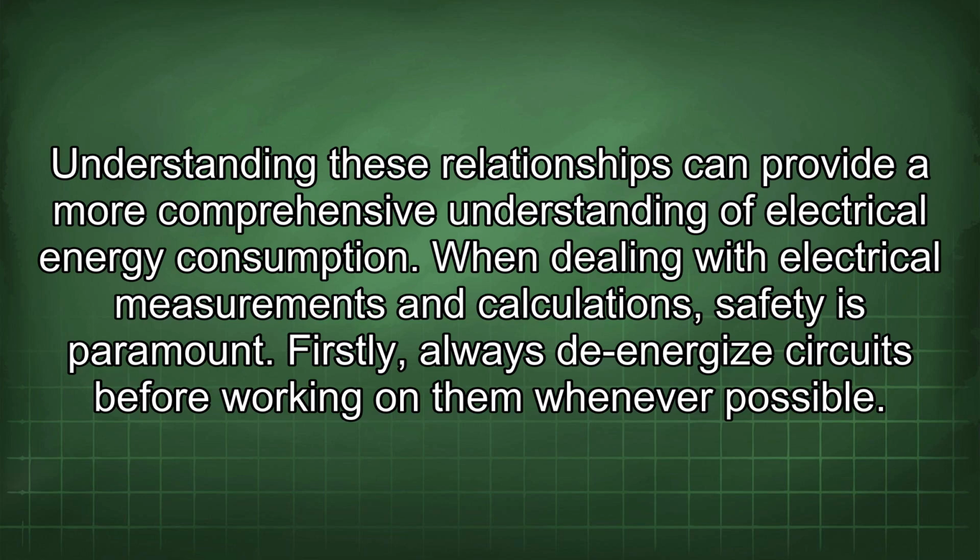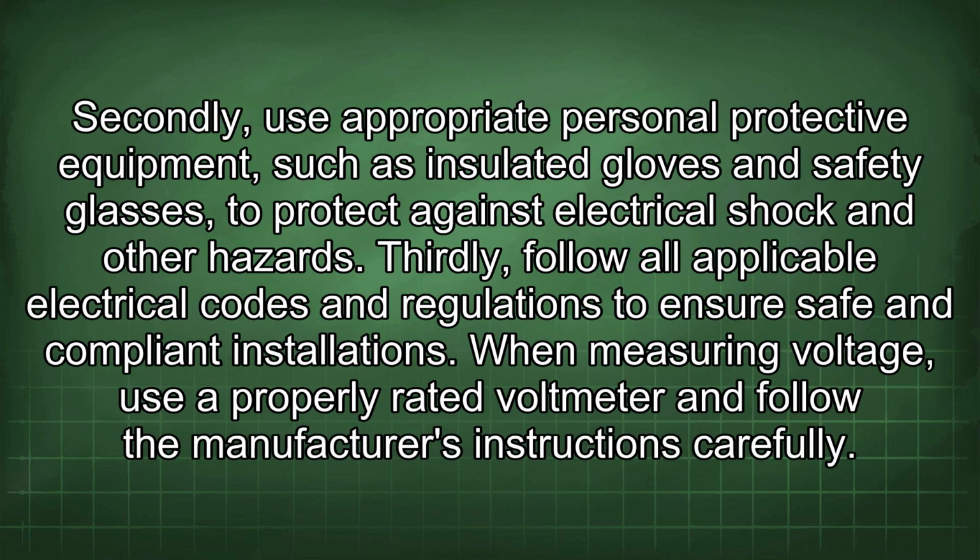When dealing with electrical measurements and calculations, safety is paramount. Firstly, always de-energize circuits before working on them whenever possible. Secondly, use appropriate personal protective equipment such as insulated gloves and safety glasses to protect against electrical shock and other hazards. Thirdly, follow all applicable electrical codes and regulations to ensure safe and compliant installations.